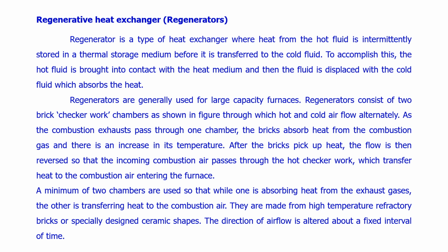The regenerator, another type, is a special type, the regenerative heat exchanger. It is used for large capacity furnaces. It consists of two brick checker work chambers as shown in the figure, and hot and cold air flow alternately. As the combustion exhaust gases pass through one chamber, the brick absorbs the heat from the combustion gas, and there is an increase in temperature.